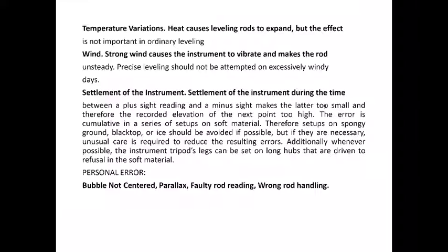Then some temperature variations can cause the leveling rods to expand, but again, we can neglect this error. Strong winds can cause both the instruments to vibrate, so that can affect the readings a lot, and it is advised to wait for a little bit and then continue with the work.